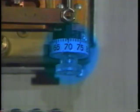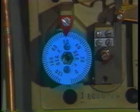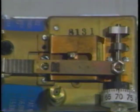What differences do you notice between the controller group and the transmitter group? Well, the most conspicuous difference is that all the instruments in the controller group have set point dials. The transmitters don't. Less noticeable is that each of the controllers has a sensitivity slider adjustment. The transmitters, on the other hand, have a dab of red paint on the sensitivity adjustment. This indicates the sensitivity was precision calibrated at the factory and should never be tampered with.